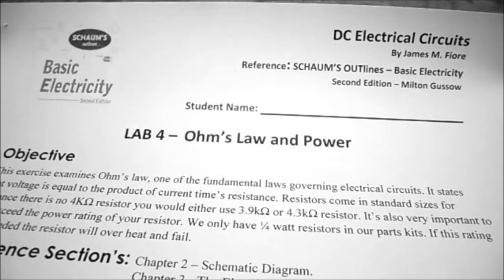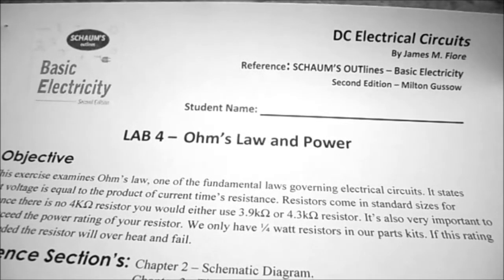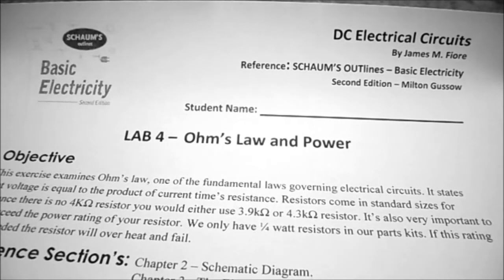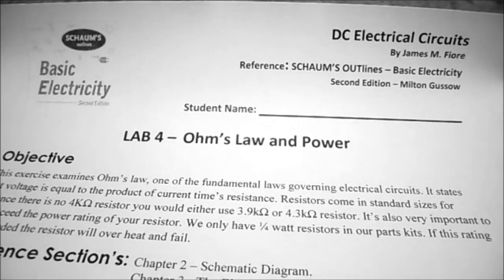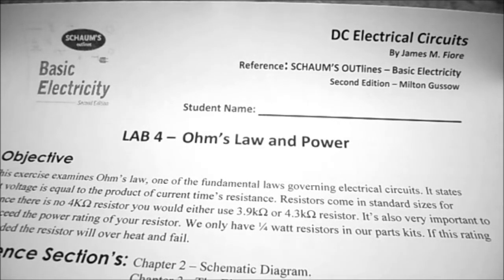We also have to be mindful of the wattage of these resistors. We're going to be using quarter-watt resistors. And we also need to know how much power is going to be dissipated by each resistor so that we do not exceed its wattage rating, or else it'll overheat and fail.